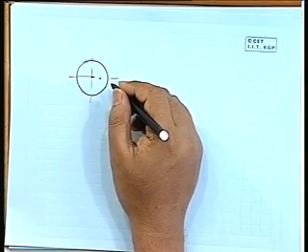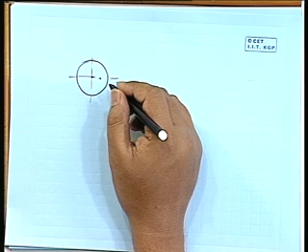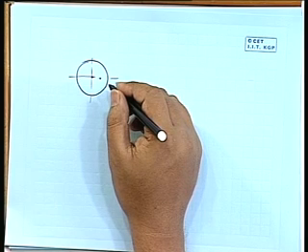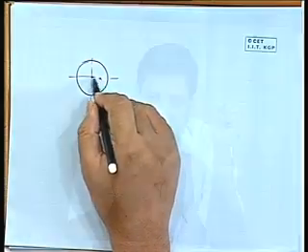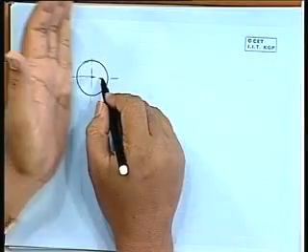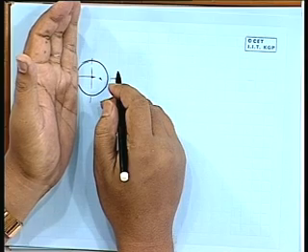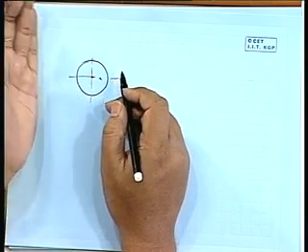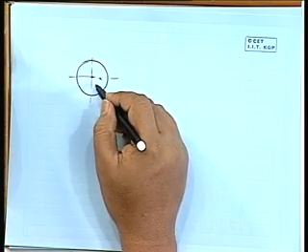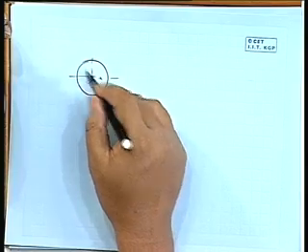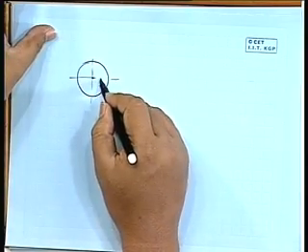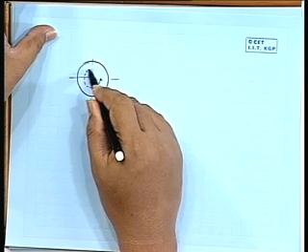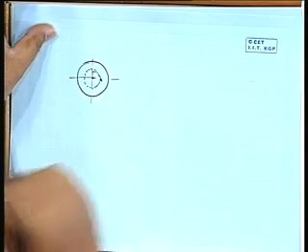If we follow the approach we applied for a rectangular cross section with one directional eccentricity, you can find the range of this e, so that the limiting point will be here. In a similar manner, if it is here, because here also it is a line of symmetry, you will get a core having a circular cross section.